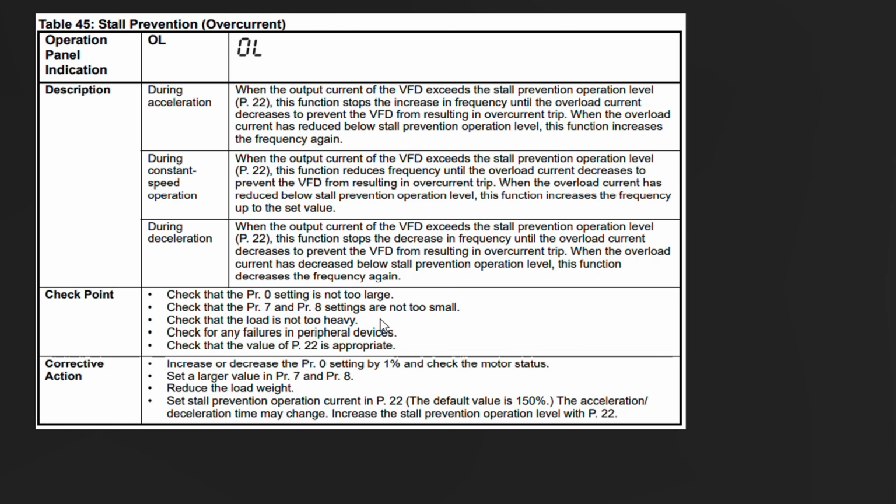This also could be a reason. And the third reason is that your motor is rated higher than required, or your motor is overloaded with the load. This also could be the reason. So you need to check these things, and if you have checked that acceleration is proper, deceleration is proper, and your